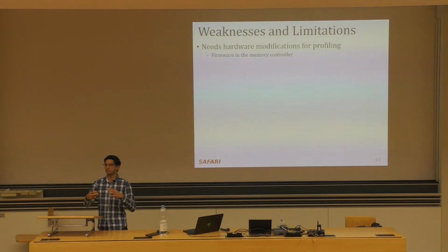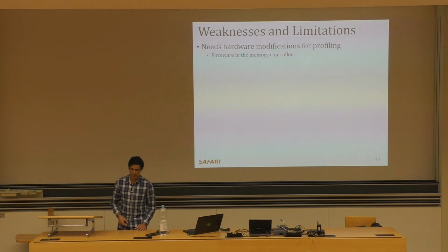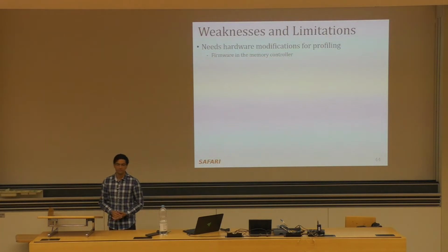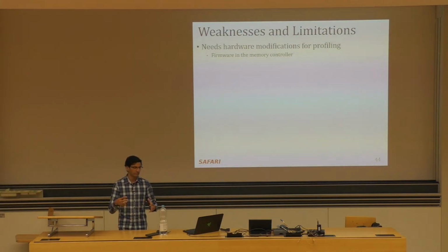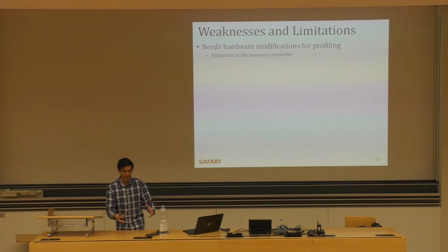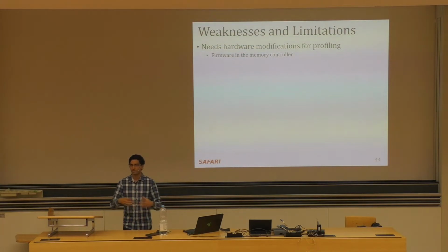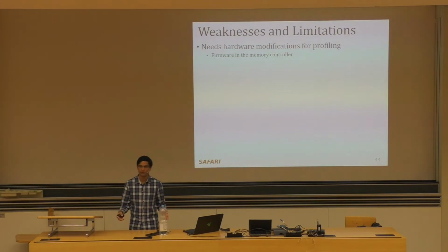And a rank, if you remember, is the level right below a channel. And so it's a huge region of DRAM, right? And so we have to change the refresh interval for this entire region at once, or not at all, right? And so when we're profiling, we have to somehow save that data that's already written there, and then we need to do our profiling, and then we need to copy the data back. It's a very extensive process, and it requires some sort of hardware support.